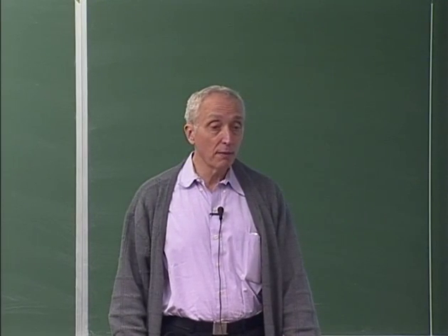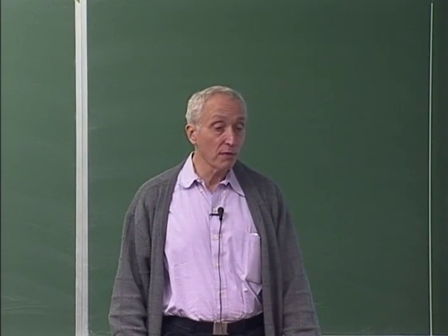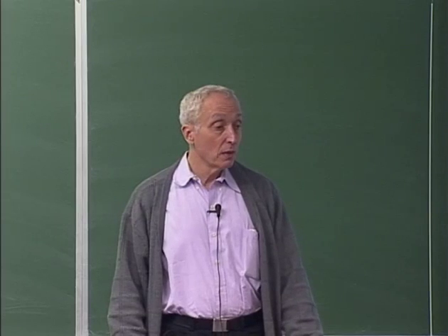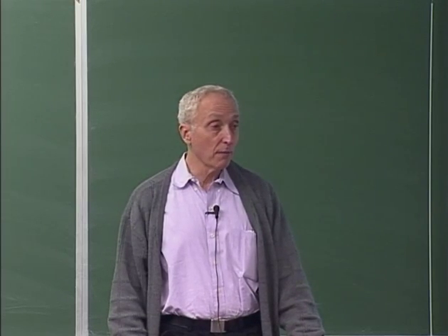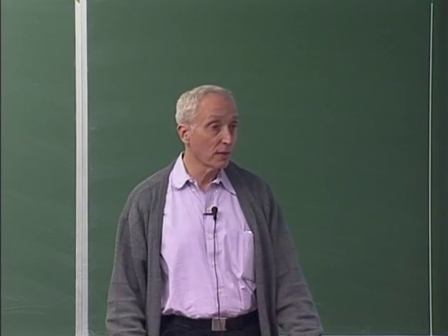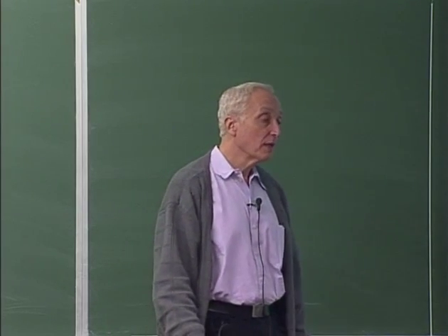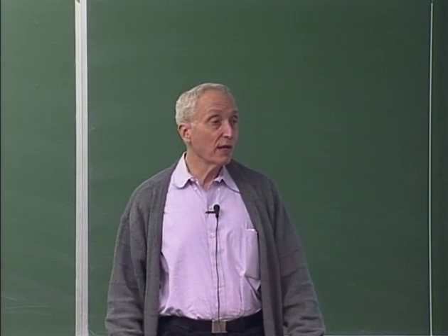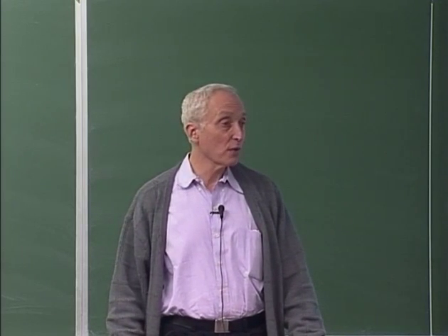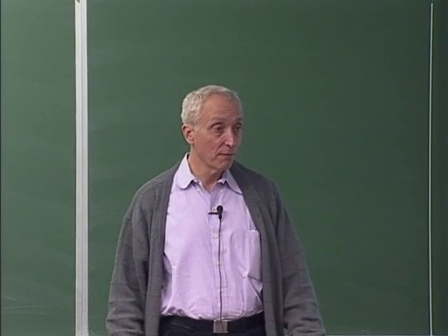And what the Monte Carlo method basically says, you have some random parameters like geometry and material properties. Why don't you generate a very large number of structures and analyze each one of them?